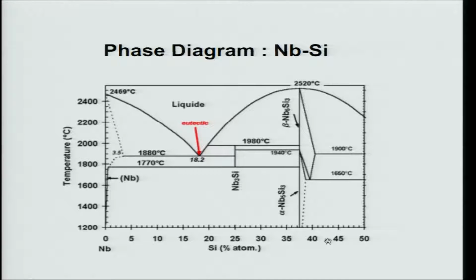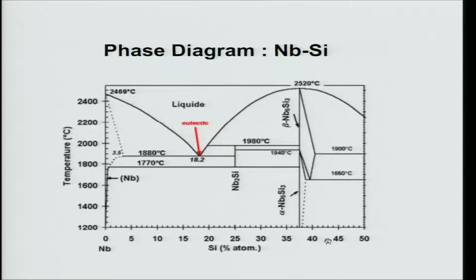In liquid solutions, suppose you take water and add sugar. So, water is a solvent and sugar is the solute. Similarly, here in a solid solution, niobium is a solvent, silicon is a solute. Why is silicon a solute? Because silicon percentage is very small, maximum is about 3.5%. So, this reaction will produce niobium solid solution plus Nb3Si. Nb3Si is an intermetallic phase.